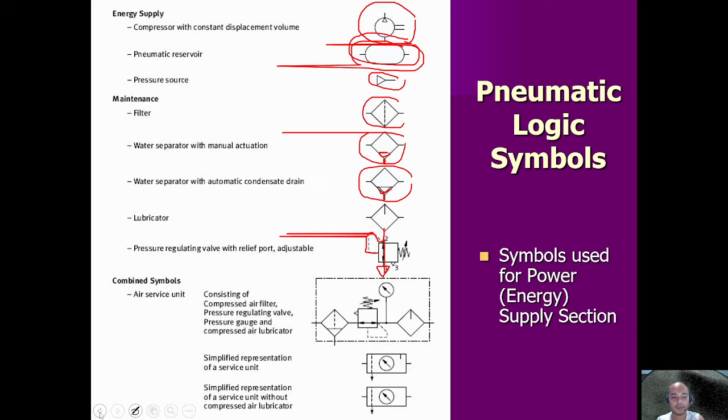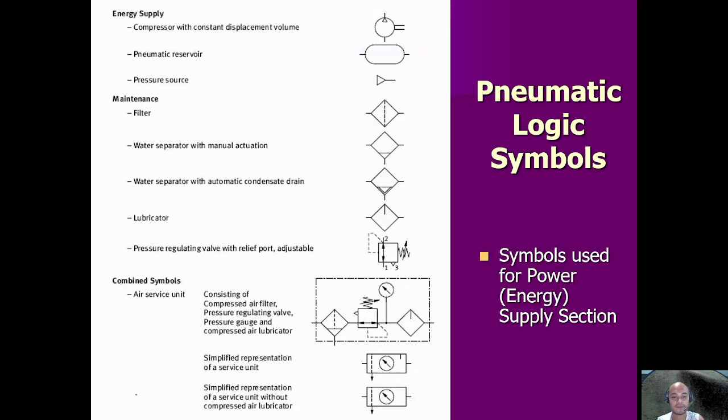But if the pressure comes from the bottom, it will go straight outside, and then that pressure, depending on the pressure, will give a signal here on the valve to close or to regulate the pressure. So the higher the pressure that comes out, the higher the regulating pressure inside the valve, so that the pressure that will go out will be regulated or controlled. Okay, so that's how it works.